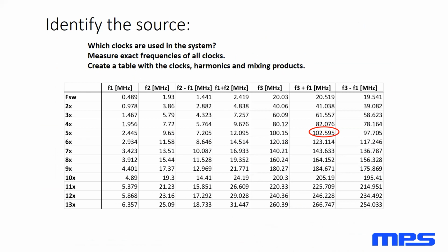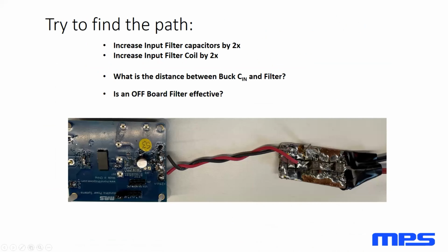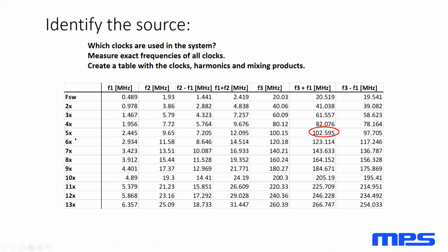I think this is just a snapshot. Ideally, you want to expand it as much as you can. These multiples, as we get out here, we should be seeing less and less energy, and generally you're going to see it cut off, maybe around 5 or 6. It's going to depend on your system, but making sure that we expand this out, because this can be an aha moment. I've seen this before with a particular system I was testing where there was a very standout frequency. So making sure that this table is expanded out as much as possible will help.